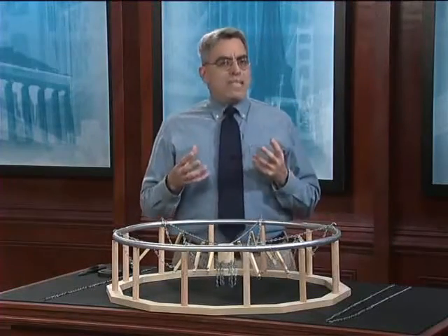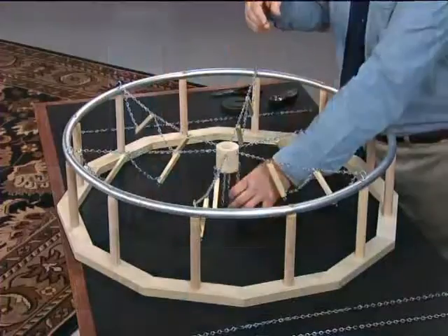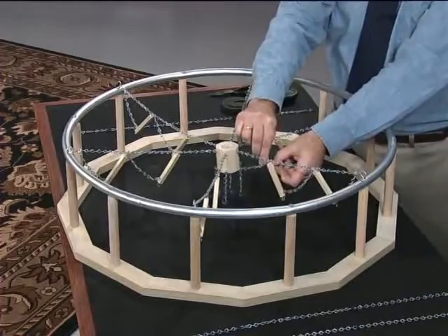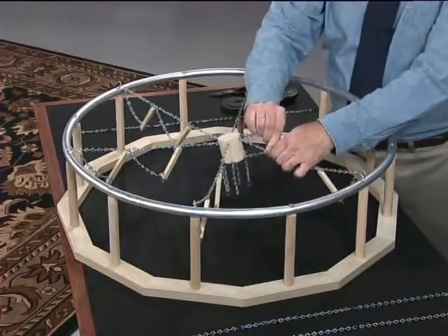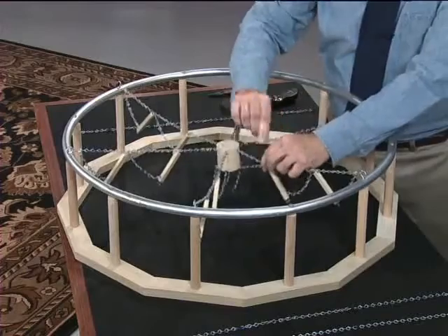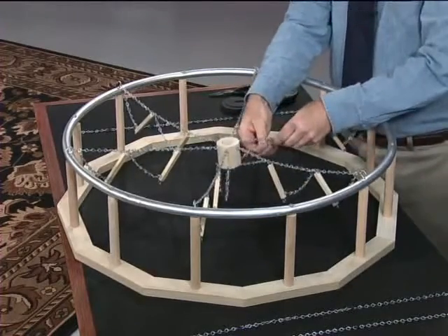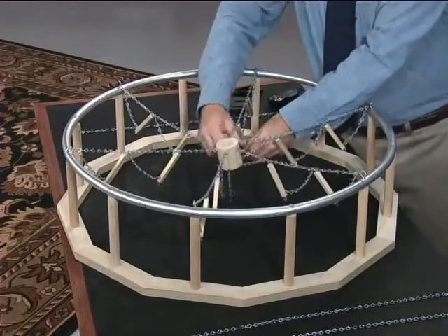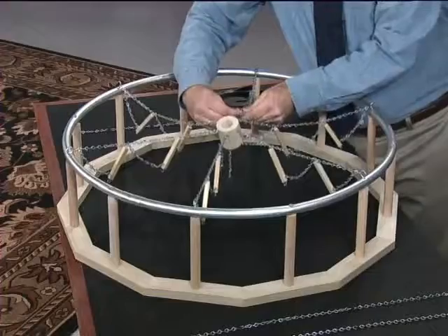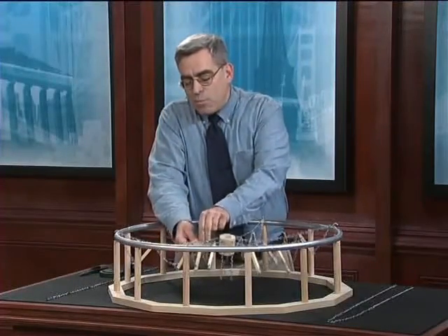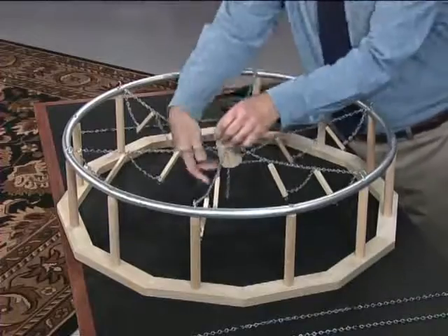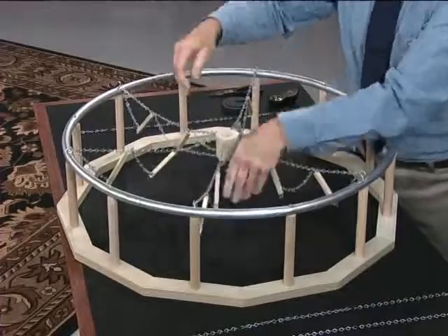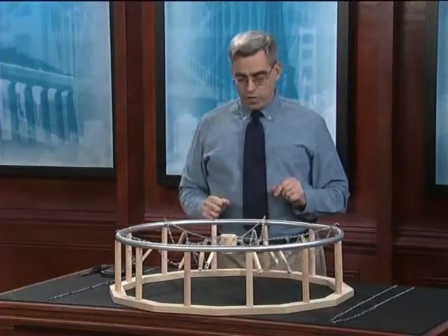In order to put the dome together, I'm going to start by connecting this series of cables which are draped down from the bottom of the tension ring back up to the main cable. And in doing so, I would ask you to note that as I attach these cables, that tension ring actually begins to lift upward. And indeed, this is one of the critical characteristics of the cable dome, that as it is assembled, it actually raises itself up without the aid of any additional temporary formwork or shoring. That's the first step in the creation of the cable dome.